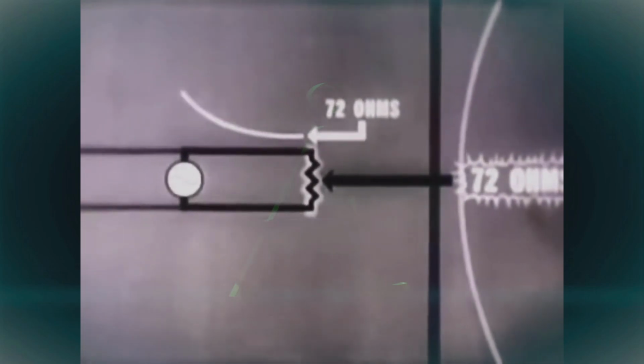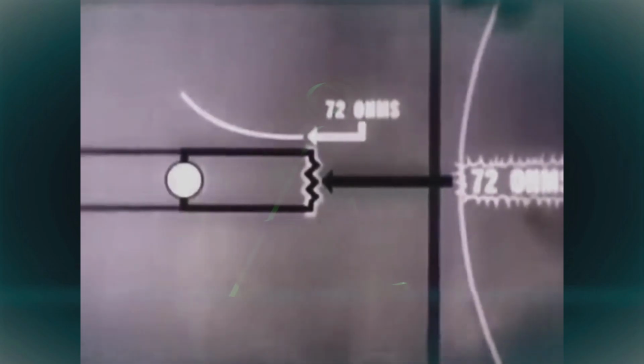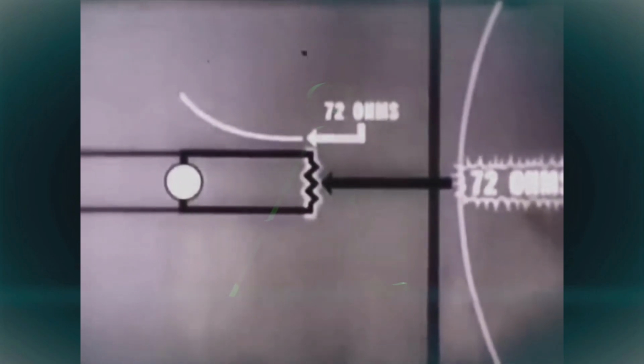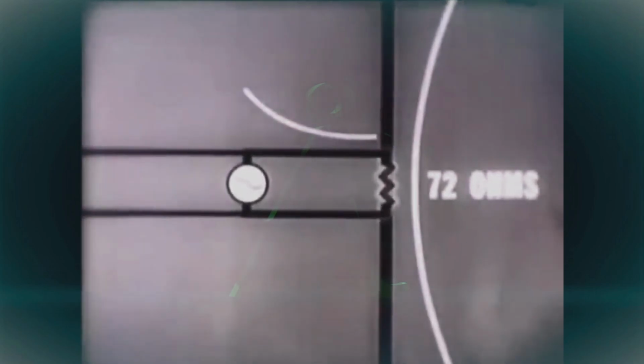Now, supposing we put a resistor in the closed end of the line, say 72 ohms. Now we know that our impedance value at this point is 72 ohms. This changes our curve a bit, decreasing the impedance value at the generator end of the line because the standing wave is no longer at maximum amplitude. Now let's bring our antenna into the picture again, connecting it to the closed end of the line and removing the resistor.